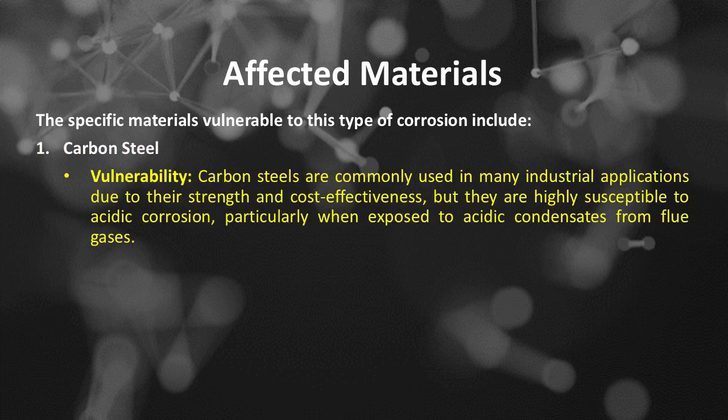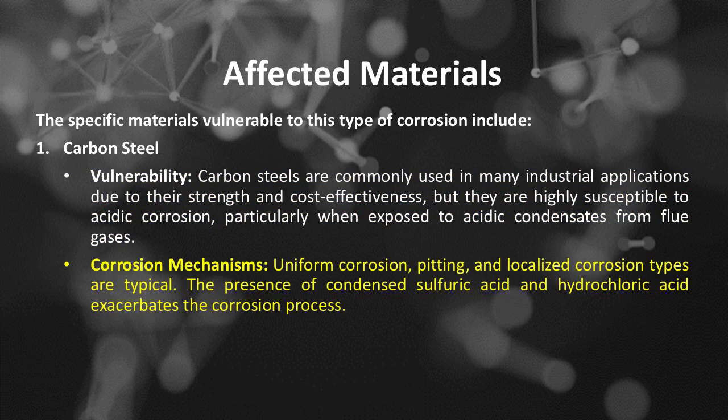Carbon steel vulnerability. Carbon steels are commonly used in many industrial applications due to their strength and cost-effectiveness, but they are highly susceptible to acidic corrosion, particularly when exposed to acidic condensates from flue gases. Carbon-steel corrosion mechanisms: uniform corrosion, pitting, and localized corrosion types are typical. The presence of condensed sulfuric acid and hydrochloric acid exacerbates the corrosion process.